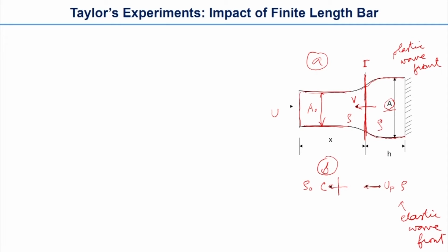So on the right hand side, rho naught is the initial mass density, and the compressive wave travels through that part and compresses the material, making the actual density higher. So now we will try to derive some relations between strain, stress and impact velocity. So we will see how to go forward.